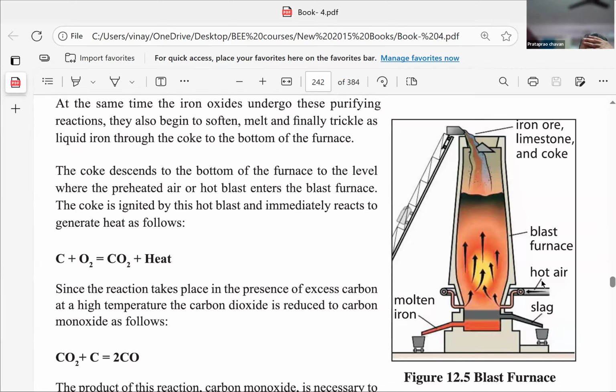Thirdly, if I can preheat the air and give very hot air to the furnace, it will add to my efficiency, because preheated air helps. For preheating this air, can I use these gases which are already at 700 degrees centigrade? It's a very high temperature. Can I use this temperature to preheat the air? Then naturally you will require a heat exchanger, air to flue gas. And then you will have to tell me the performance of that exchanger.